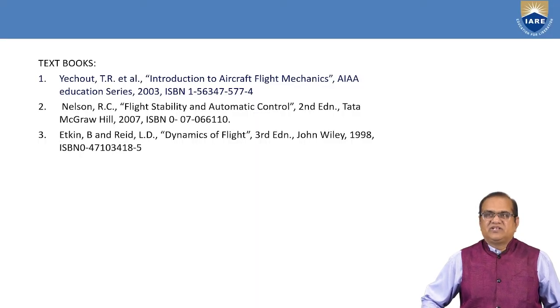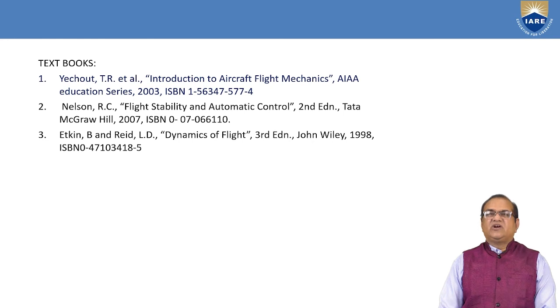Thank you very much for joining the class, and I am ending here. Hope you might have liked this class, and hope you will learn the effect of the wing on the aircraft's static longitudinal stability and how this wing is producing Cm alpha positive or Cm naught positive or negative, and how we can counter these things, and the effect of the tail will be discussed in due course of time.